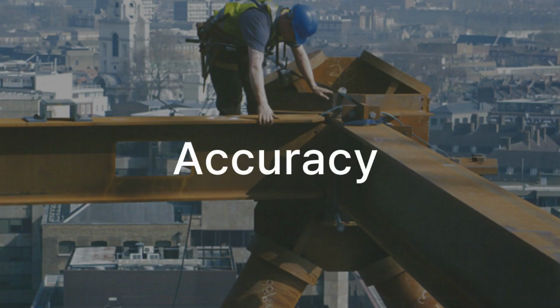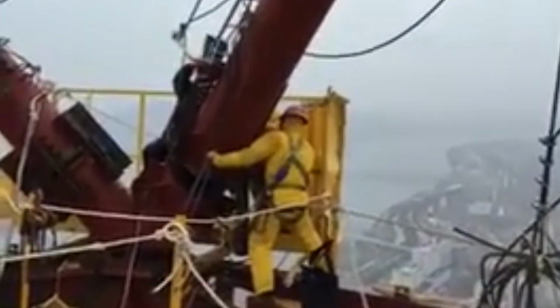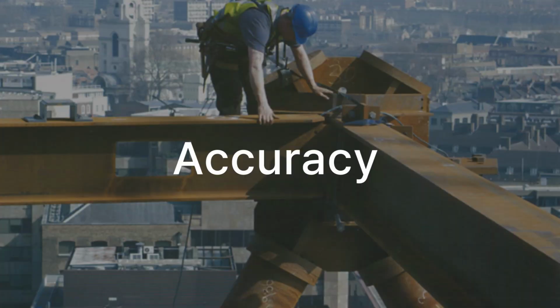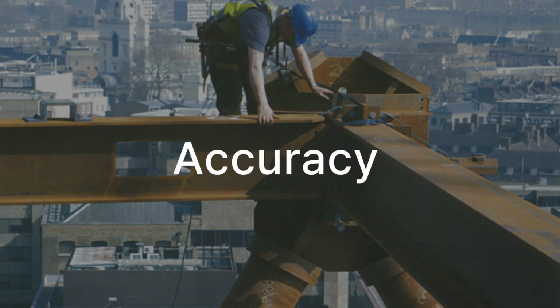By the way, did you know that accuracy is the most crucial factor in diagrid construction? Even a slight error in the angle, length, or connection position of the components can greatly shake the stability of the entire structure. It's really critical. So, for precise construction, it's essential to thoroughly check for any discrepancies with the drawings. We must verify whether the diagonal length and angle of each diagrid module match the design drawings. To do this, a precision check is necessary.